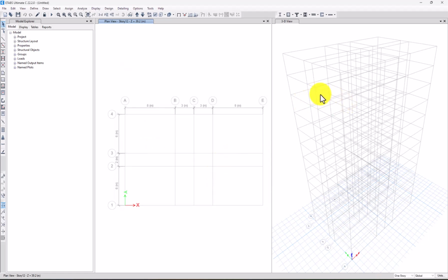We consider the structure as uniform, but it's not practical. You can actually use, for example, 3 floors or 4 floors with one type of section, and the top is a little bit lower, because the stiffness should be distributed in the top. The length is going to be higher, so the displacement will be more. So you must be using a slightly lower stiffness element, so 80 centimeters is lower, so it'll be 60 in a 3 section.